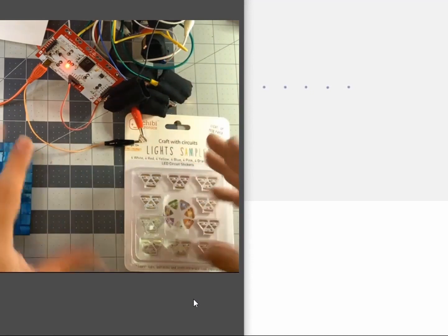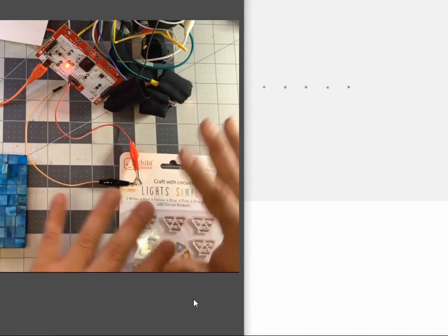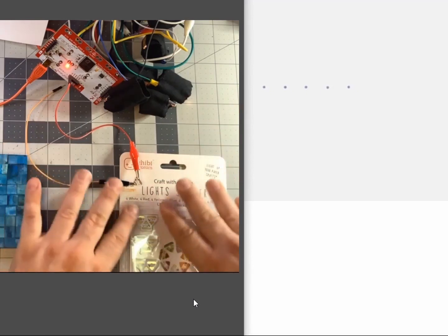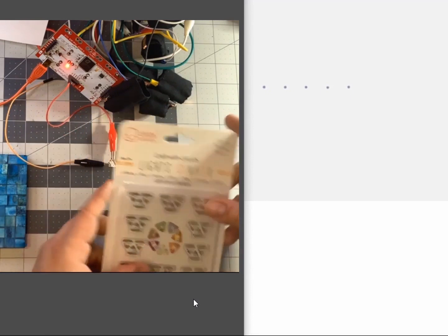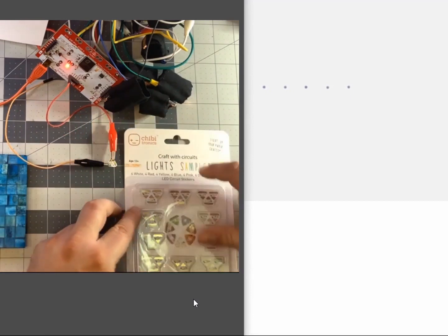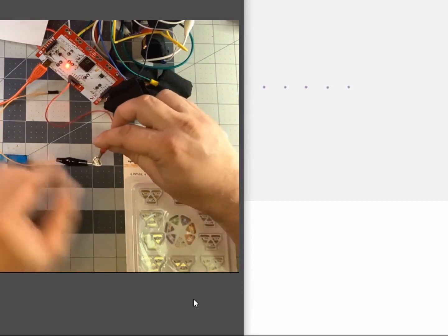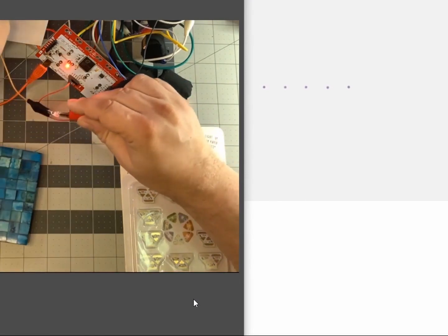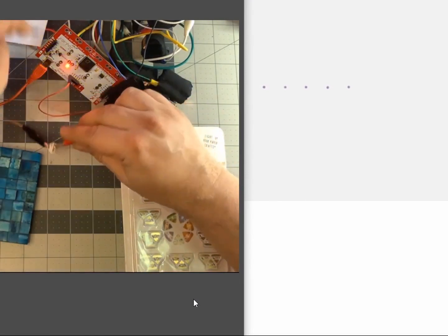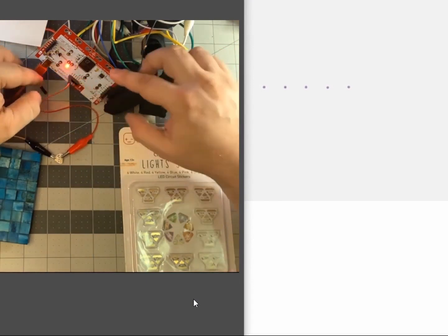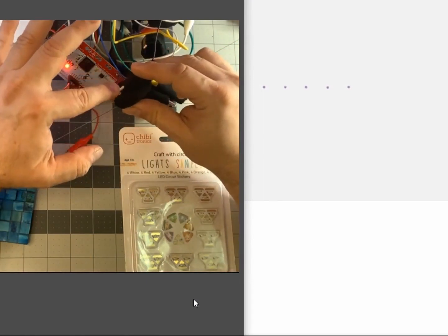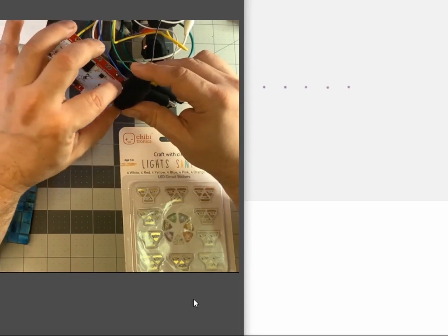So what I'm going to be doing is breaking each of those jobs down and working on them individually. It is specific that in order to get this LED system to work, I will have to run this 5-volt as a separate circuit. It isn't going to run off the same one. That would confuse the button effect.